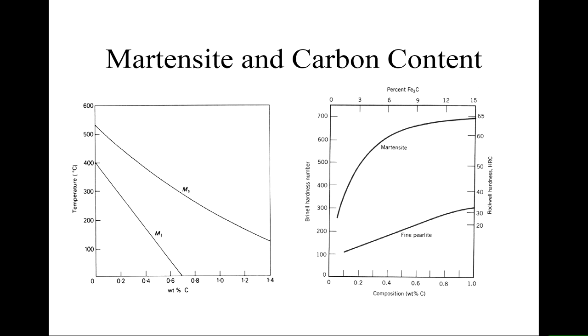And the difference is relatively small at low carbon contents, but as the carbon content goes up, martensite becomes much, much harder. Now, typical construction steels with around 0.2% carbon go from about 100 to about 400. So it's a factor of 4 increase in strength. And that has a consequence in brittleness by forming the martensite. So if you can slow the cooling rate down to stop martensite formation, then that's a good thing to do.